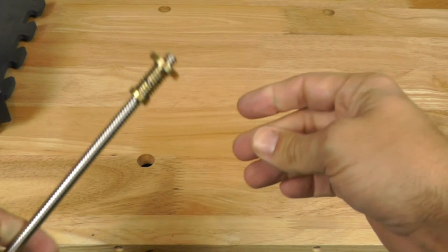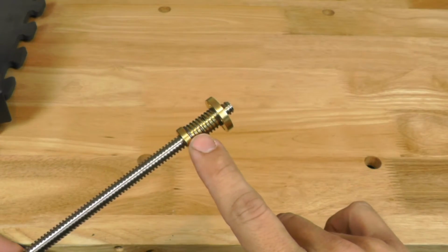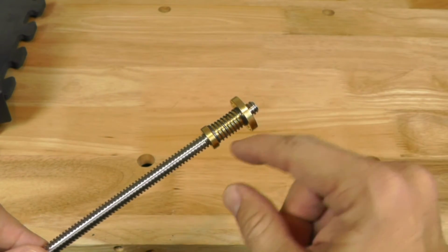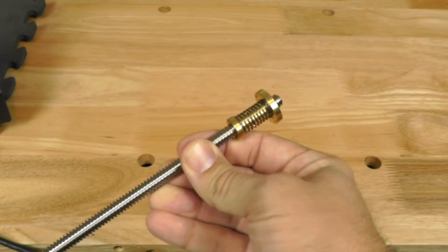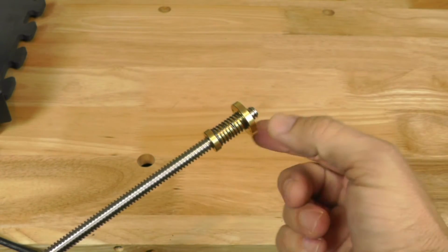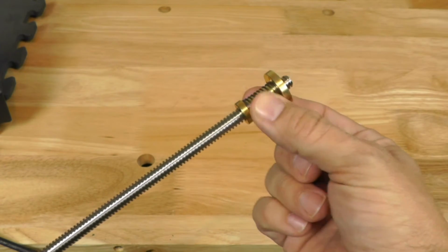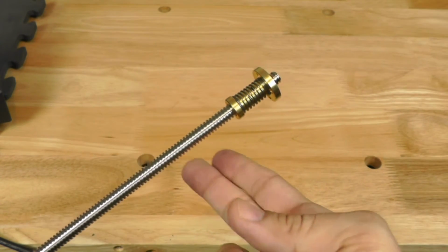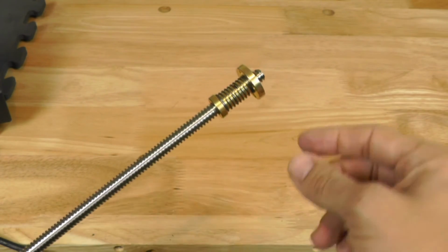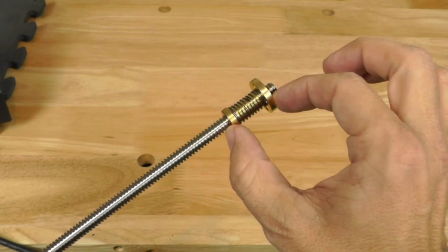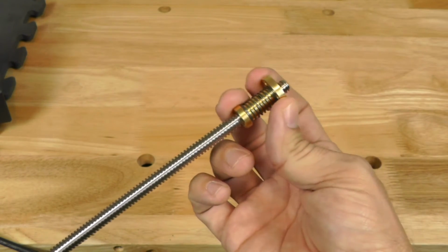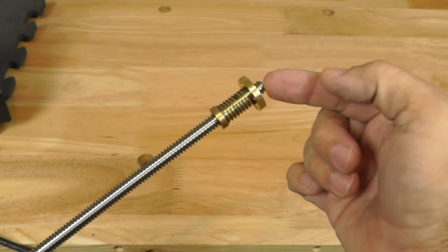Well, there's what's also called an anti-backlash nut, and this one right here has a spring as well as a bottom piece that loads this so that it doesn't shake on us. You hear this one. Notice no rattle because there's tension on this, creating a tighter fit on this screw.